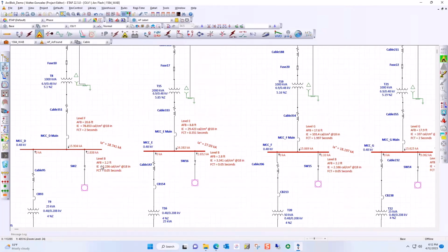Once the calculation loads, as you can see here, all the annotations on the bottom right belong to the bus bars. The reason I know that is when you move and highlight the annotation, it highlights the bus. And then the higher annotations are the annotations belonging to the line side arcing faults. So as you can see here, drastic differences.